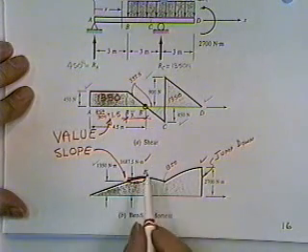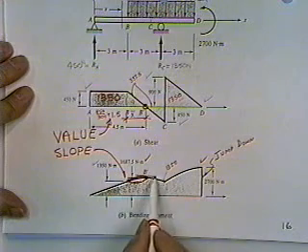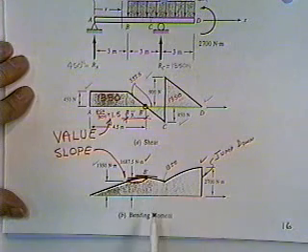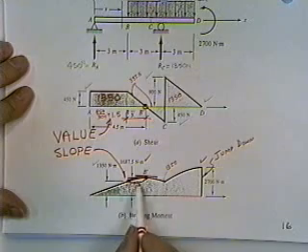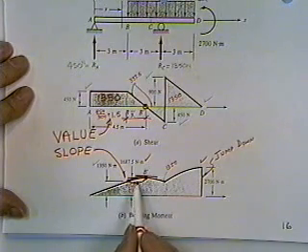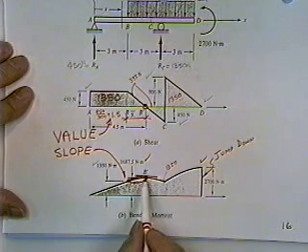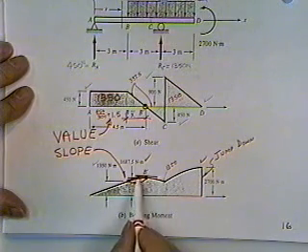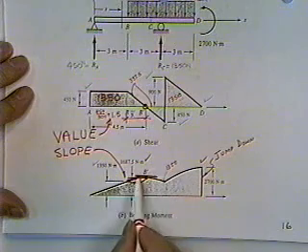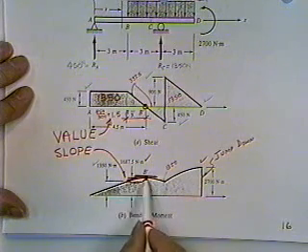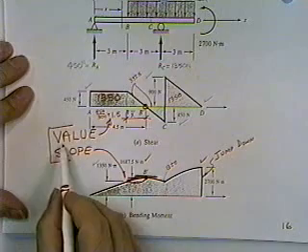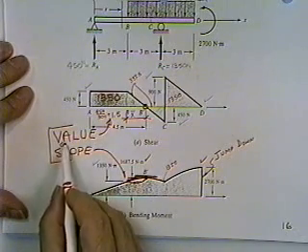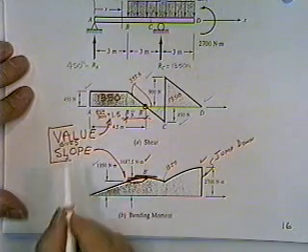Therefore, on the next diagram, it is necessary that you draw a curve having 0 slope. And that says that the bottom curve wouldn't fit, because the curve coming into B prime, if you pick the bottom curve, has a heck of a slope when it hits the end. You want the top curve, the one that has 0 slope on its end. So it's pretty easy to tell which curve using this rule right here. Value gives slope.